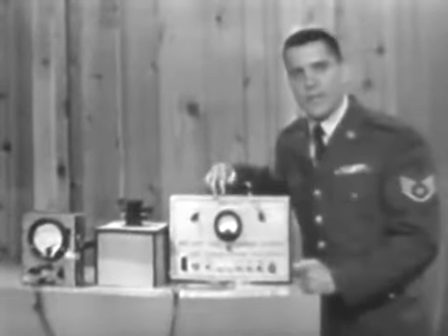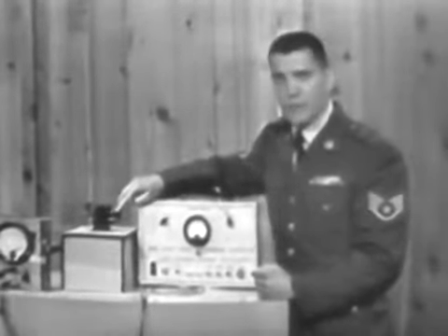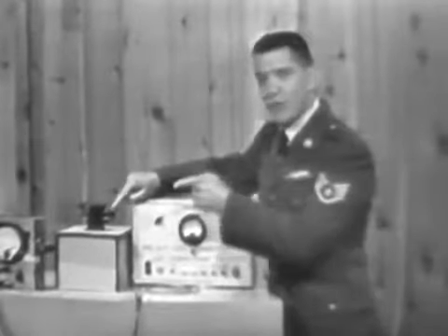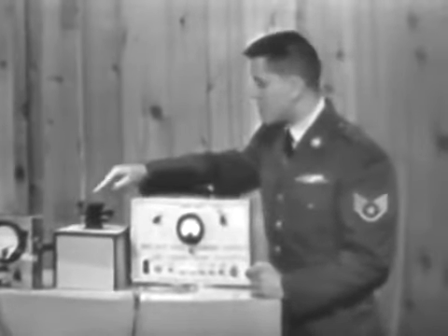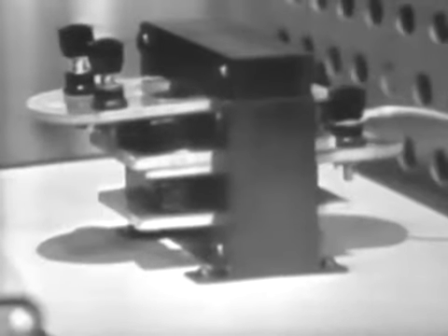Now, here I have a power supply, and from these two terminals on the power supply, we can obtain 6.3 volts AC. I'm going to apply that 6.3 volts to the primary of this transformer, and then we'll use our PSM6 and measure the voltage available at the secondary. Let's go ahead then and apply the 6.3 volts to the primary of the transformer, which, as I've already mentioned, is the bottom winding here.